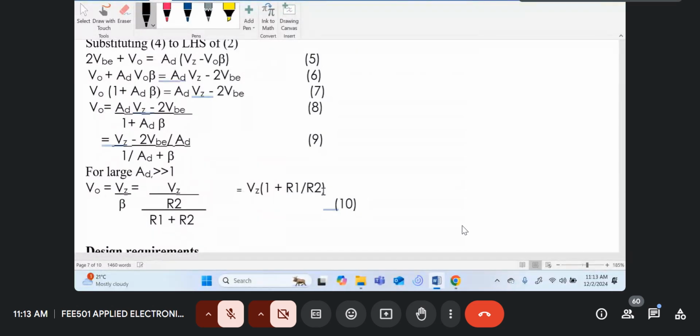So this equation also gives us how our regulator works. If it's designed properly, if you increase the load or decrease the load, the output voltage will be constant. If the input voltage V in increases or decreases, the output will still be constant. So this is how mathematically our regulator works.